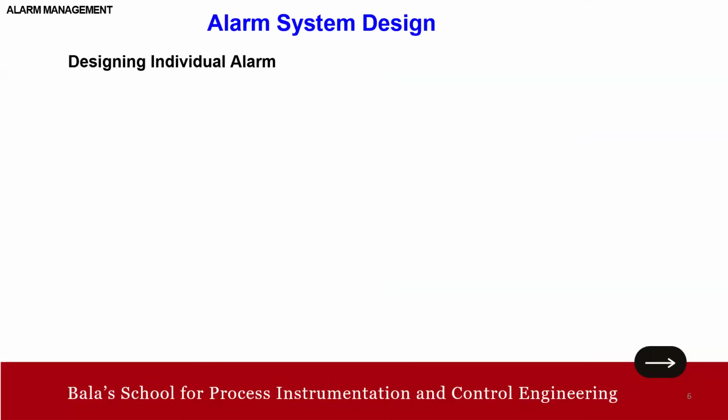That's a point. Another important one, designing an individual alarm. Every alarm configured on a system needs to go through a design process. It is not just like that, right? Every alarm we give is going through a design process. So this should include confirming whether it is justified and can be configured to support the operator. That is the main point.